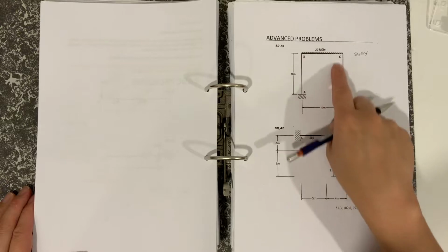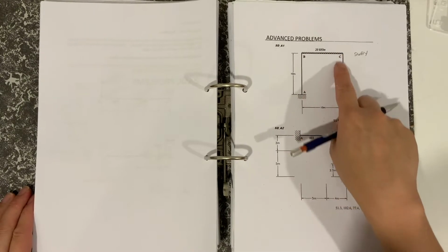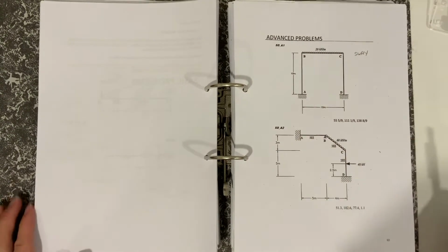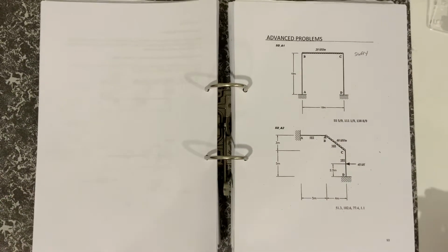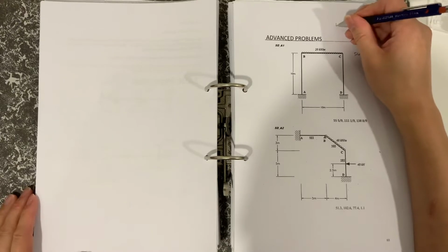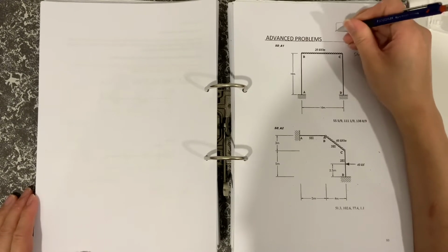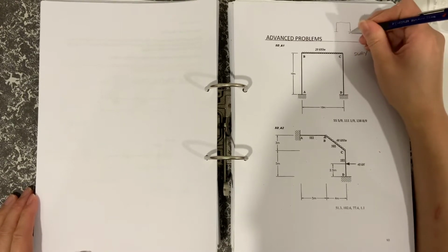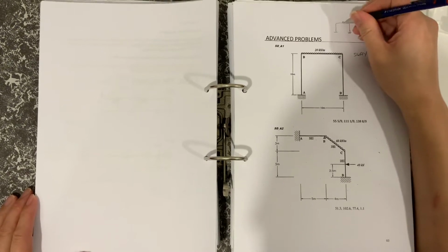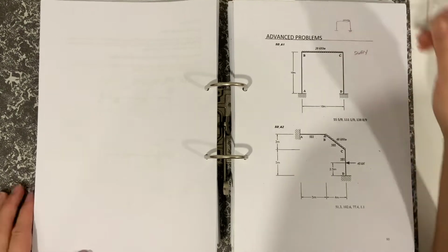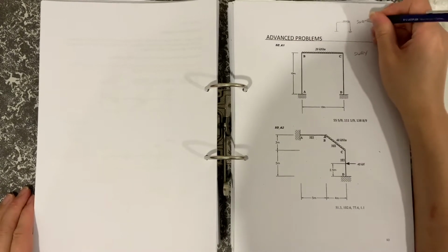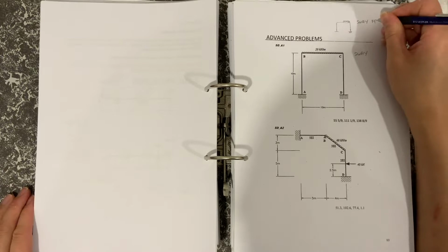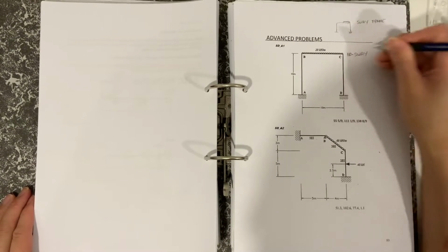So we can use the slope deflection equation for this particular case to calculate what the bending moment diagram would be. Now, for example, if we took exactly the same problem and we had the load on half the side, then this one here would be swaying. So I'll go through it later. So that would be a sway frame, and I could call this a no sway frame by symmetry.